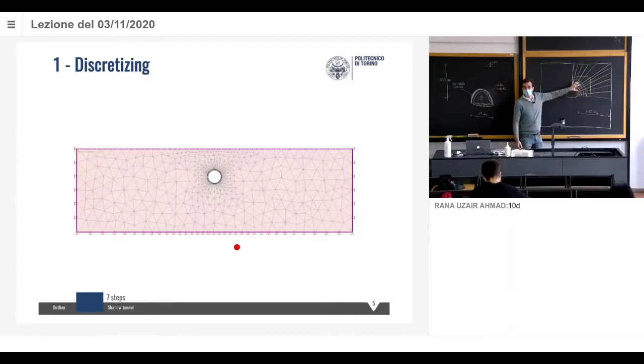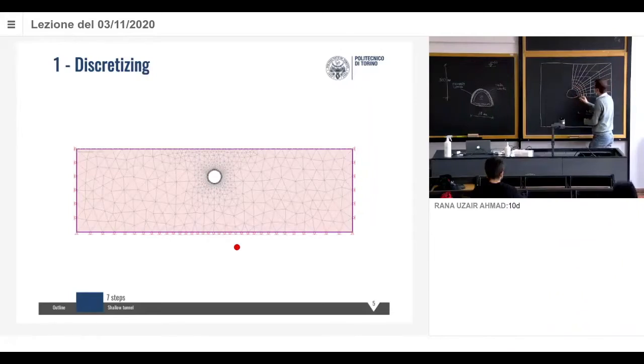we said this already. We need denser mesh in the area where we have more stress gradients. We know that already. Okay, so this is going to be a mesh we like because we have big elements down here, not as big as I made here, but maybe like this. We have denser mesh in this area. And that's it. And you can see the mesh on the slide. You have a denser mesh in this area, which is the area where we expect more stress gradients.